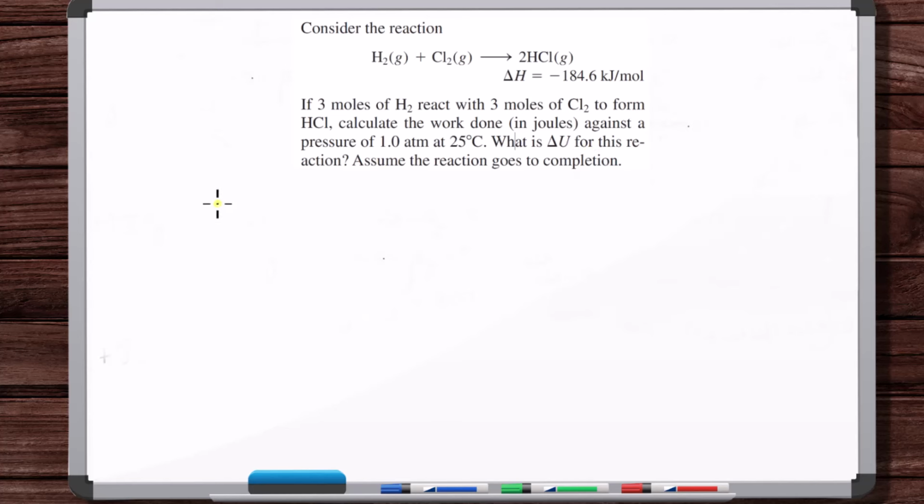Okay, so one thing I noticed is that we have 1 mole of gas here, 1 mole of gas here, so that's 2 moles of gas. And in the products, we also have 2 moles of gas. This isn't necessarily a constant temperature process, but at least the reactants and the products are at the same temperature. So going from state 1 to state 2, it's the same pressure.